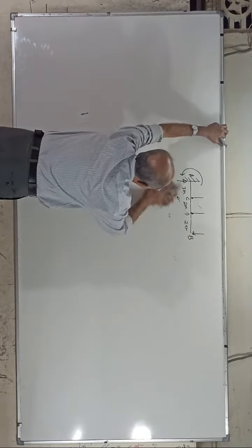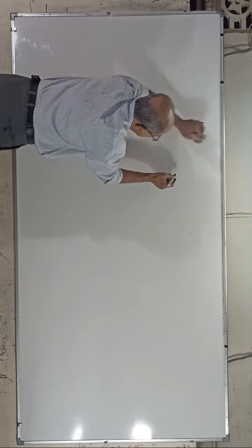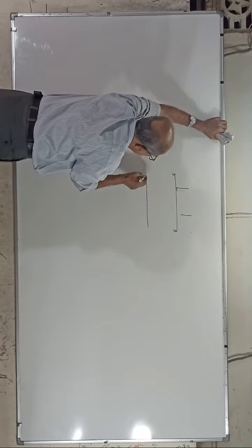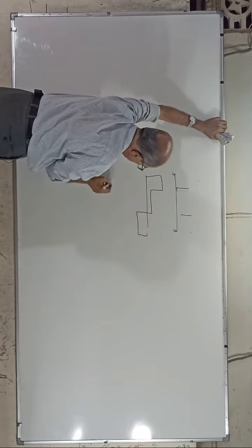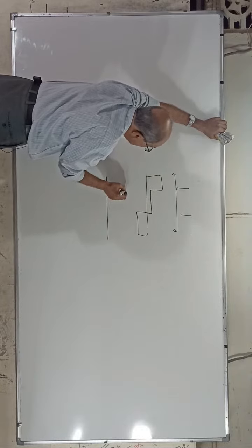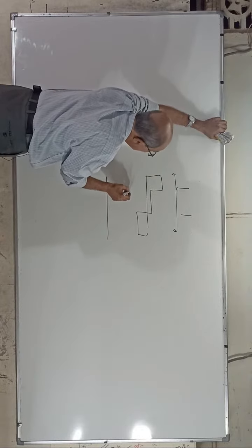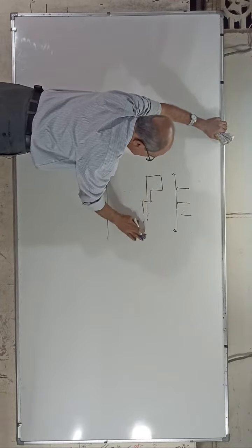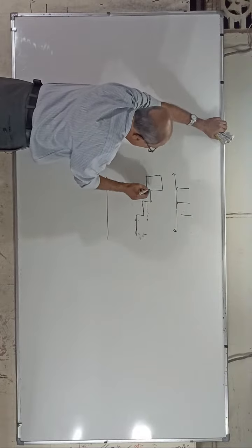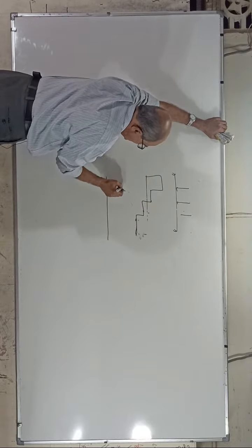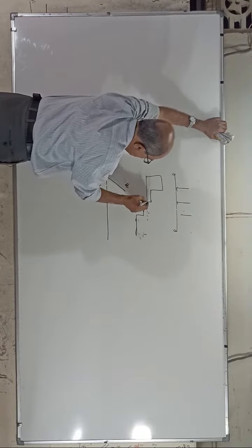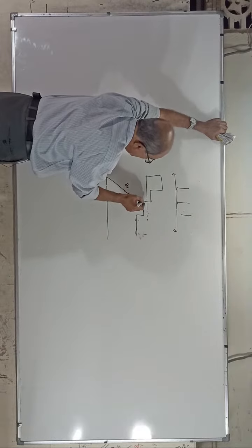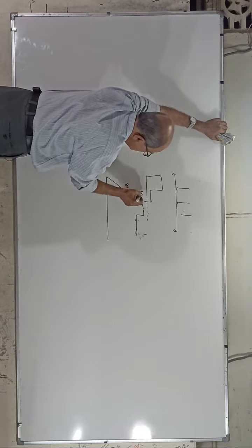And even for a simple supported beam also. See, just for example, some 2 point loads are there. SFD will come this way. BMD, they will calculate the BM here. Or one more point here, then SFD will change. They will calculate BM here, it will come 80, they will put 80 here. They will calculate BM here, it will come 90, they will put 90. No, it will come very high, 160 comes. They will draw this way.